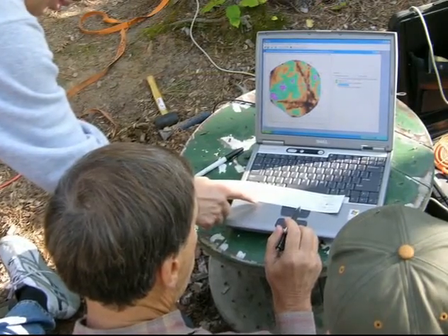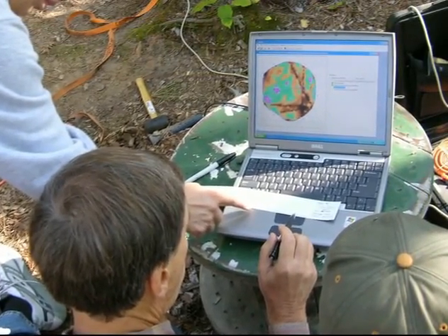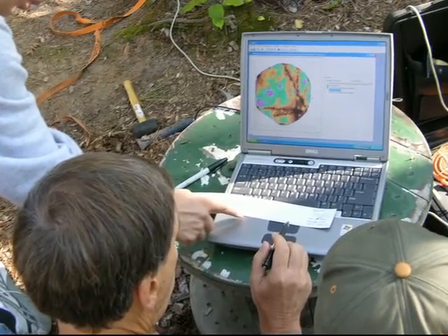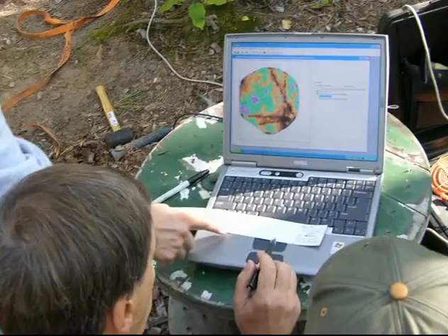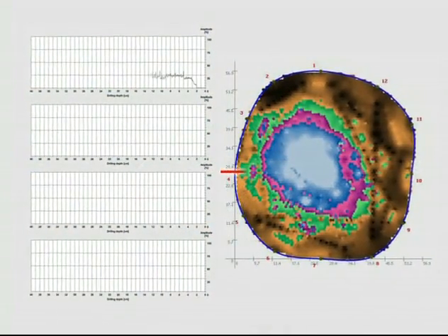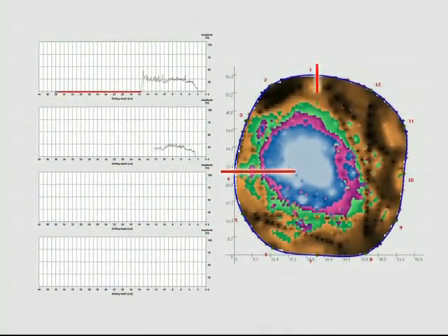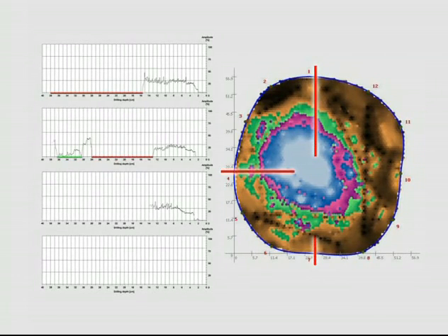The combined use of time-saving visual and single-path stress wave screening tests also reduced the use of the multi-sensor tomograph test. By using the tomograph to guide the number and direction of micro-drill tests, fewer drill holes were needed and more meaningful information was gathered.